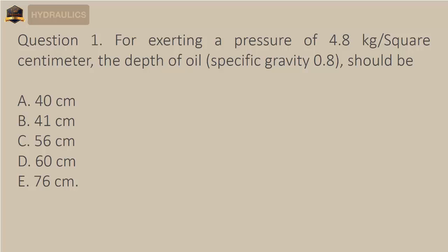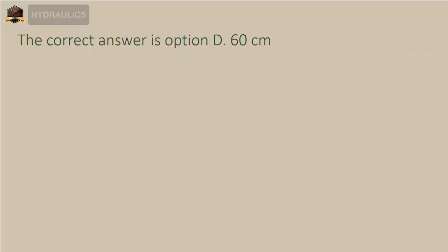Question 1. For exerting a pressure of 4.8 kilograms/square centimeter, the depth of oil-specific gravity 0.8 should be A. 40 centimeters. B. 41 centimeters. C. 56 centimeters. D. 60 centimeters. E. 76 centimeters. The correct answer is option D, 60 centimeters.